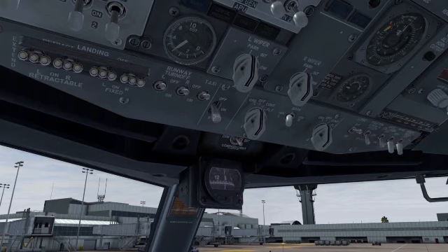There is an ignition selector switch that may select either ignition L, ignition R, or ignition both. AC buses are comprehensively discussed in the 737NG electric system lesson. From here, normal startup takes care of itself, and the pilots monitor for normal indications. Anything abnormal and a quick shutdown can be performed, placing the engine start lever in cutoff and turning the ignition to off.